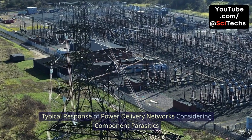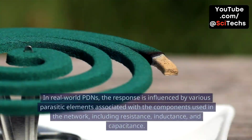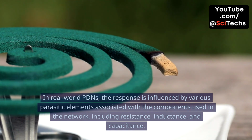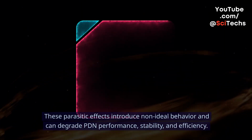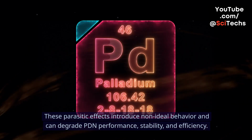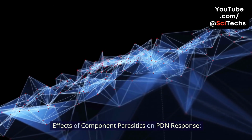Typical response of power delivery networks considering component parasitics. In real-world PDNs, the response is influenced by various parasitic elements associated with the components used in the network, including resistance, inductance, and capacitance. These parasitic effects introduce non-ideal behavior and can degrade PDN performance, stability, and efficiency. Effects of component parasitics on PDN response.